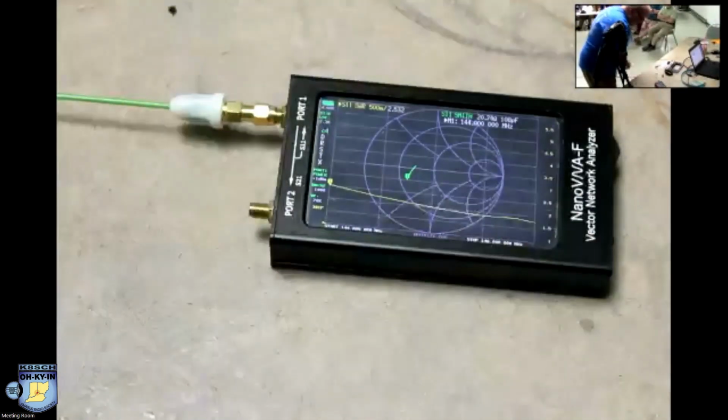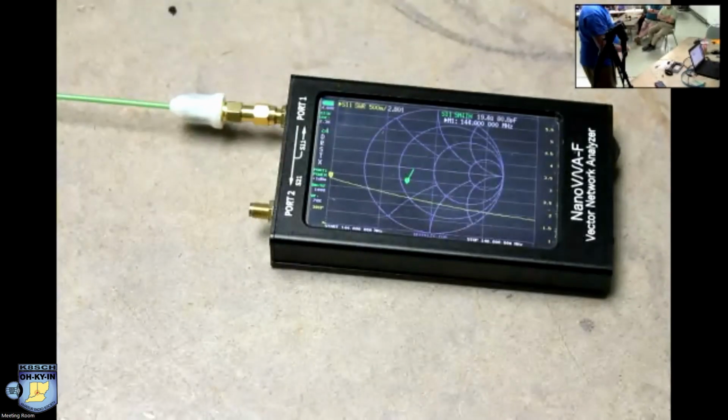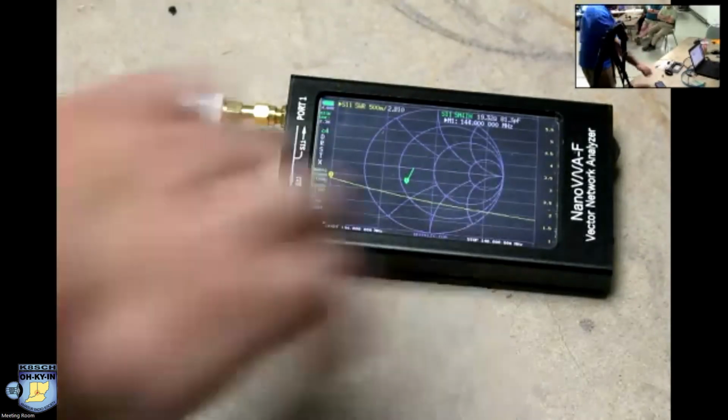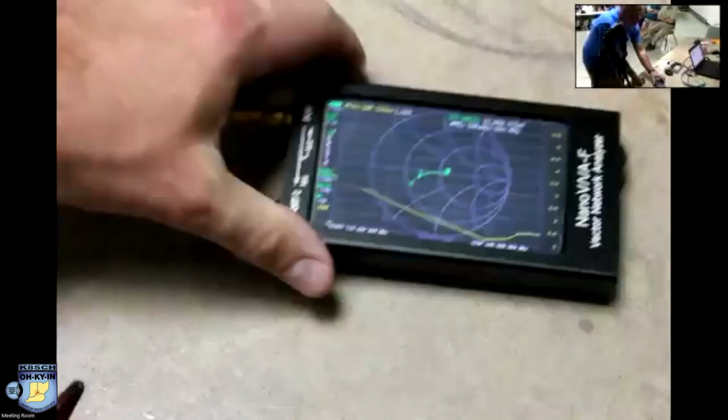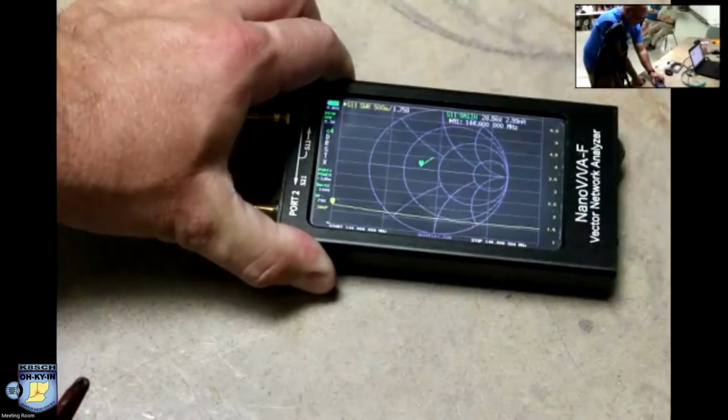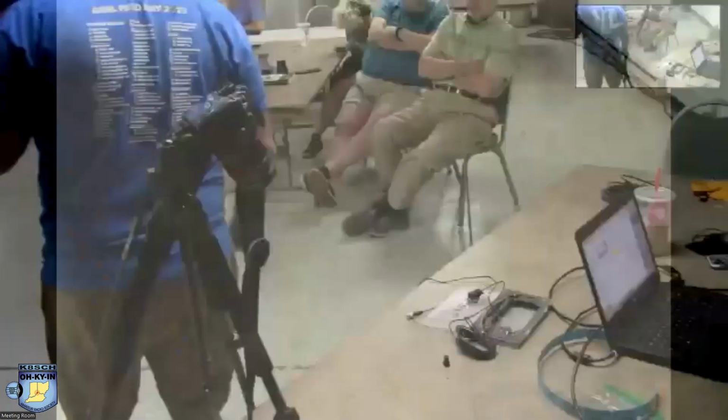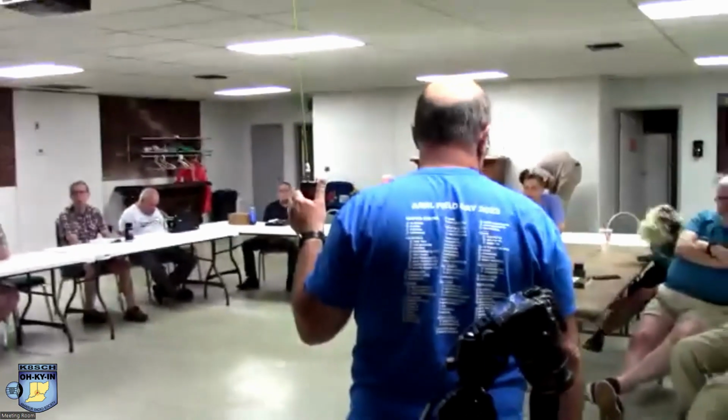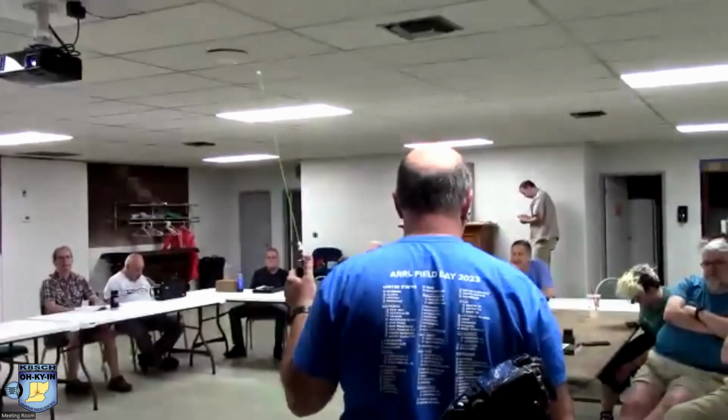So the SWR on that thing is about 2.5 across the board. Yeah. But as I said, if you come in here and start putting your hand around here, you begin to see it drop. So if I'm pulling away from the camera, so if you start holding it up like you would, yeah, it's 3 now. So yeah, this one I found weird. My other one, if you hold it up, it actually gets better. This one, when you lay it down, it gets better.